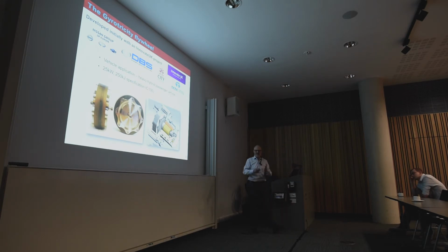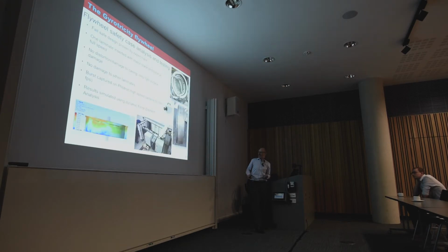That was interesting. Most automotive companies have this sort of on the shelf at the moment; they play with all these technologies just in case the law changes or the drive cycle changes. So we've got that system working. It's a very high C rating, 25 kilowatts. An 8 kilogram steel rotor could absorb the braking energy of a heavy SUV from 40 or 50 miles an hour down to 0. So the flywheel's not necessarily big and heavy.